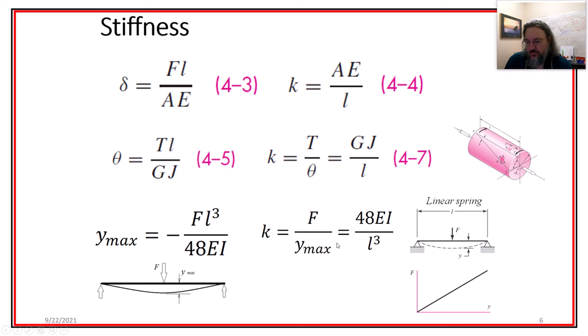And notably, this would be like a linear spring, but only up to a point. So we have to worry about nonlinear behavior. And FEA, at least in the baseline package that you would get without any advanced solving, will really be restricted to small displacements. Large displacements will start to become nonlinear, and that can become more challenging to solve. If we have to solve a nonlinear problem, you need iterations, and that can take a lot of solving power. That's usually a more expensive version if you're buying your FEA code a la carte, and quite often companies do, because they don't want to pay for something they don't need. But just be aware that large displacements is one of the nonlinear solving things that has to happen.